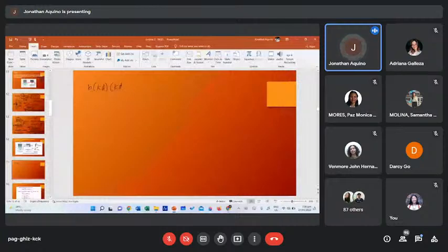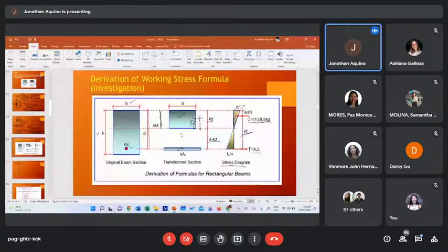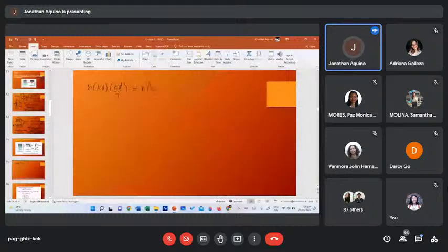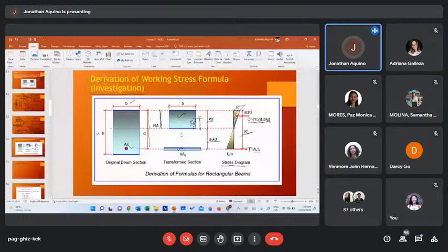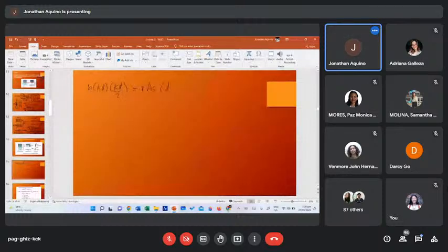So it's equal to the moment of area below. So the moment of area below is n As. Okay. Yun yung transformed area ng concrete, steel equivalent concrete, times the lever arm. So the lever arm is d minus kd, so times d minus kd.